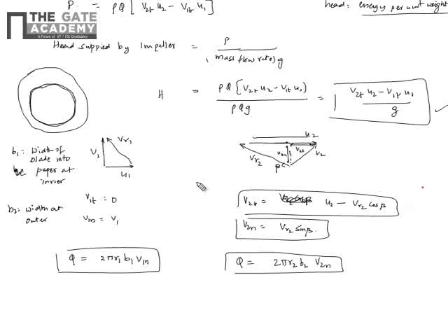So once you are able to write down velocity triangles, then you can express tangential and normal components, and then it's all about getting the blade angles. So the blade angle at the inlet is beta 1, at the outlet is beta 2. So first is drawing the velocity triangle, the second is writing the head expression. So we'll do a problem on this so that all these relations will be covered. Let's do a problem.